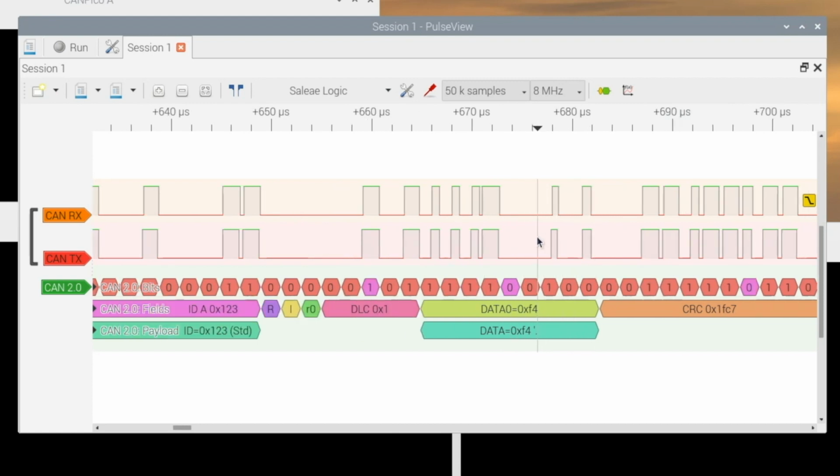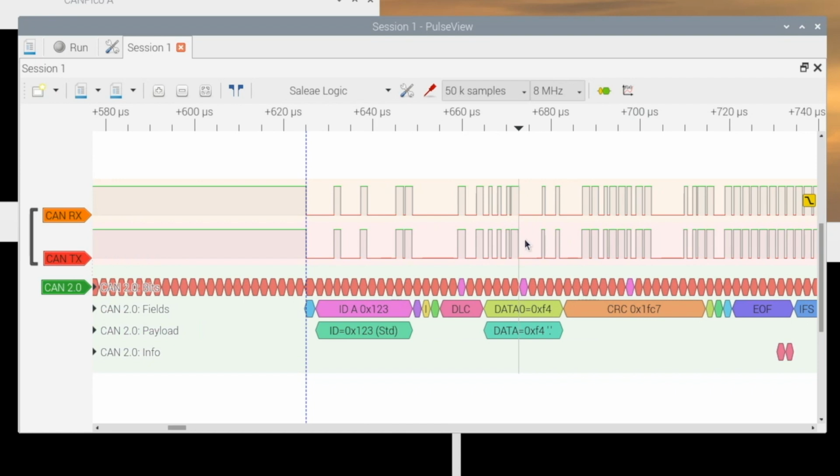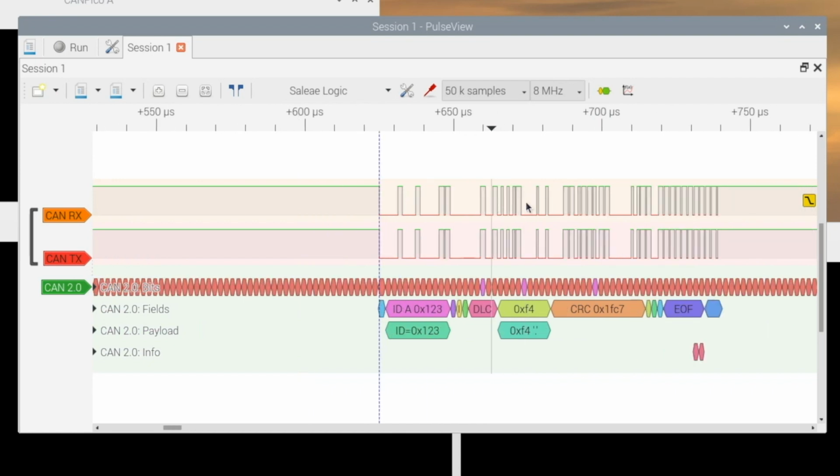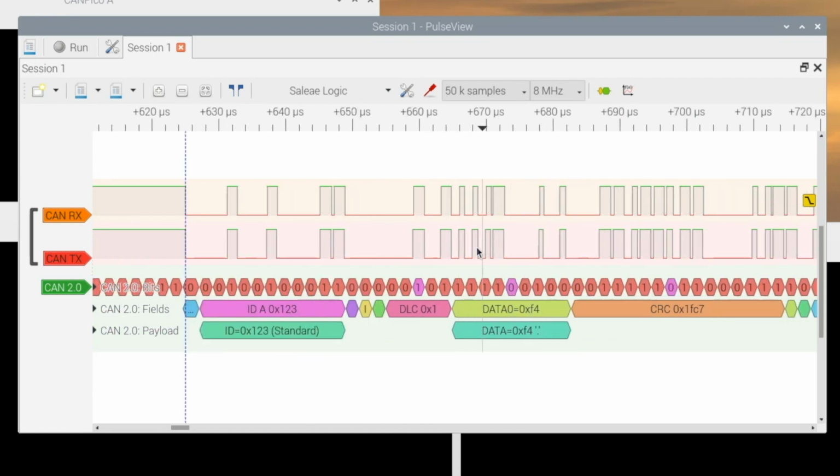So we've managed to encode 2 different payloads inside the one frame by manipulating the CAN bit sync protocol, and by sending a carefully crafted sequence of 1s and 0s to the CAN TX pin, so that we can get 2 different receivers to see 2 different payloads.